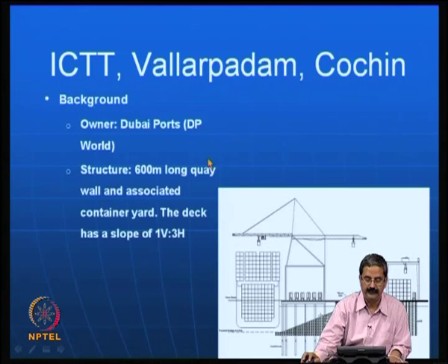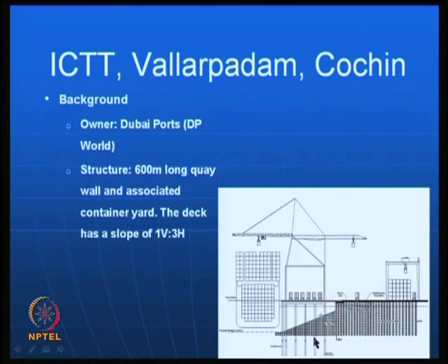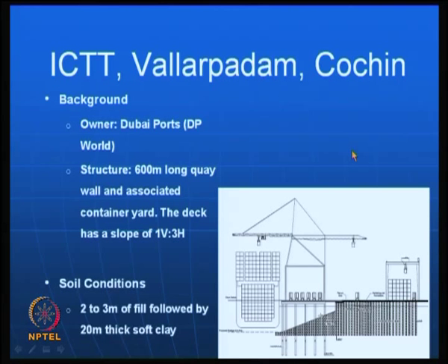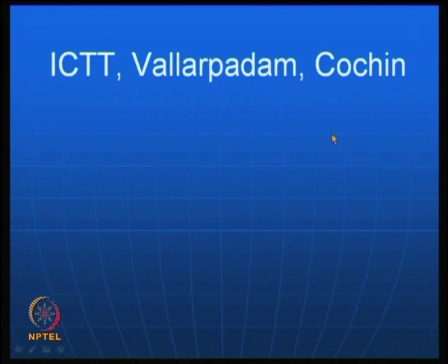So, it is again a 600 meters long quay wall and the associated container yard. The deck has a slope of 1:3. Soil conditions: 20 meters of thick soft soil. The first 2 to 3 meters is a fill, and it is quite tough, and there is another medium stiff material.